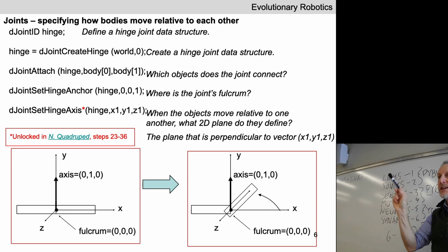notice that I'm not changing the orientation of my marker. We can then think about the object changing its yaw, pitch, and roll. It can rotate about the x-axis. It can rotate about the y-axis, and it can rotate about the z-axis. So it can change its x, y, and z, and it can change its yaw, pitch, and roll, which gives us the 6 degrees of freedom. If you define two separate links in your simulation, you've got 12 degrees of freedom. Each of the two objects can move along at 6 degrees of freedom.